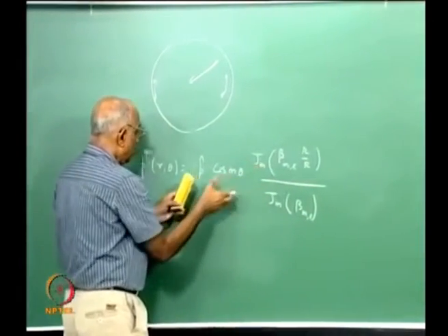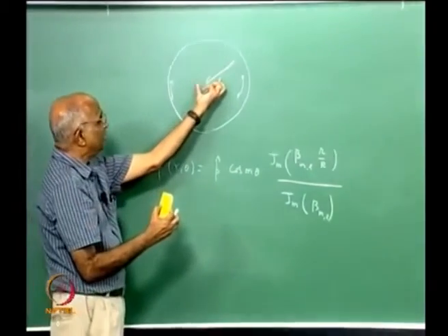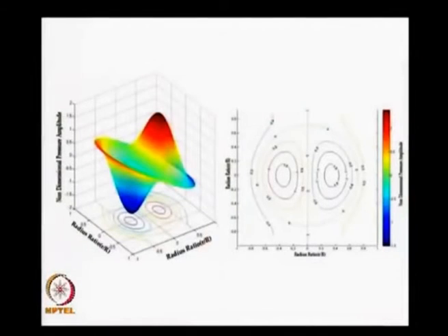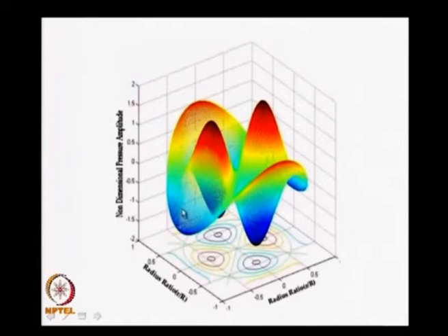And when I put the things together, I have pressure oscillations in this form, and therefore if I couple both the tangential and radial together, I have at different places different values of pressure perturbations. This is the combination of the first tangential and the first radial. Then the next one is the second tangential and first radial, in which case I have different places where the pressure perturbations are a maximum.